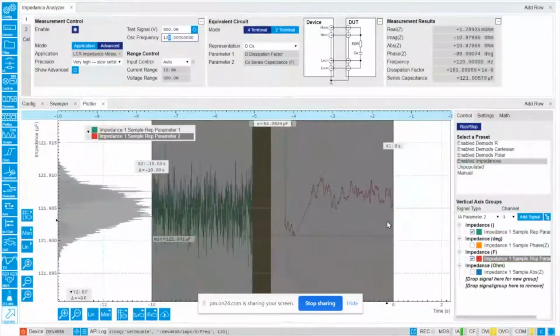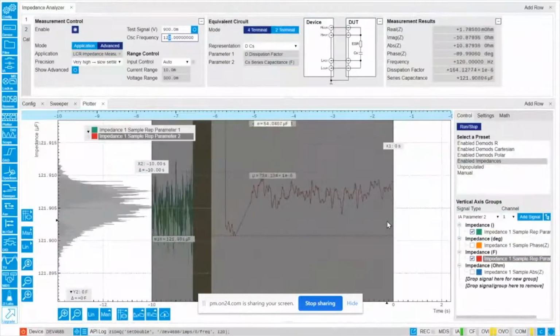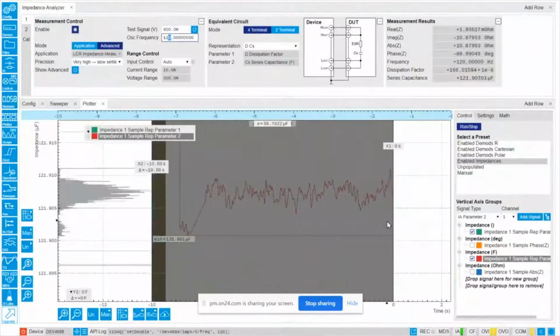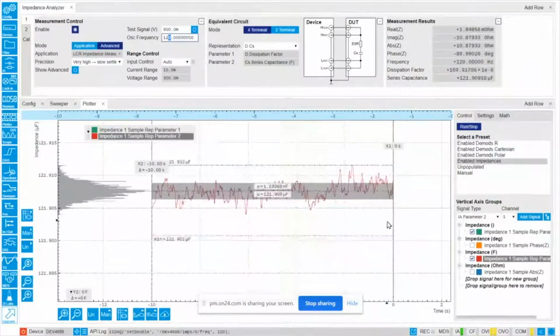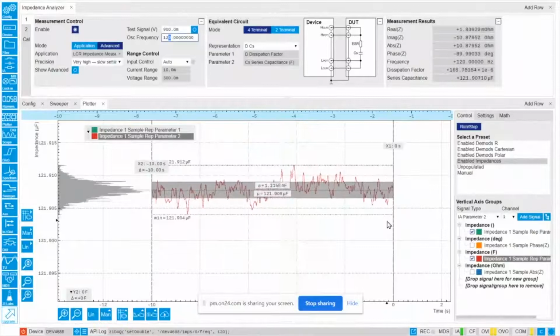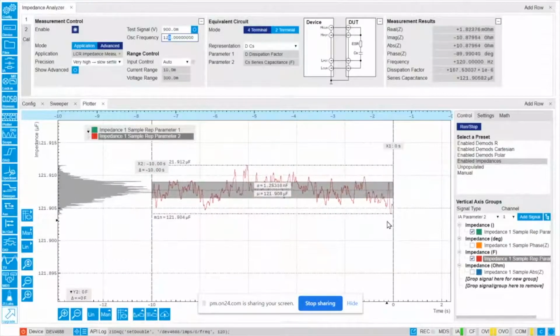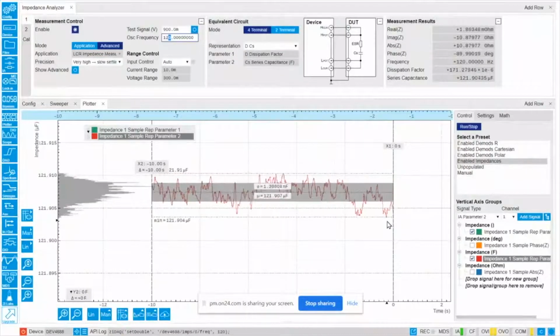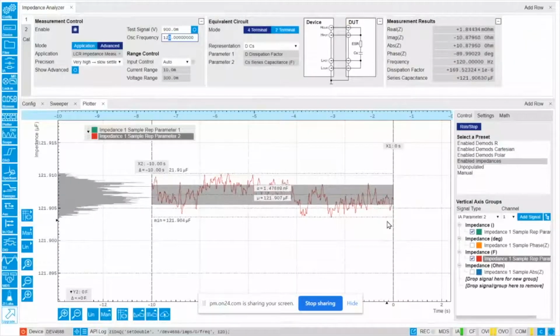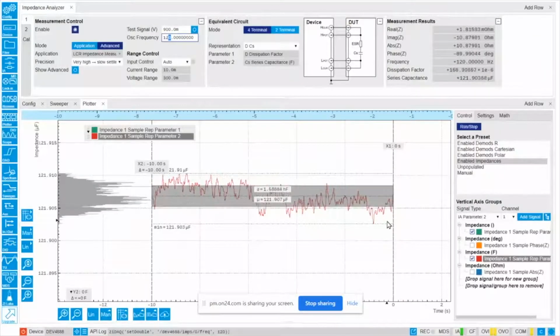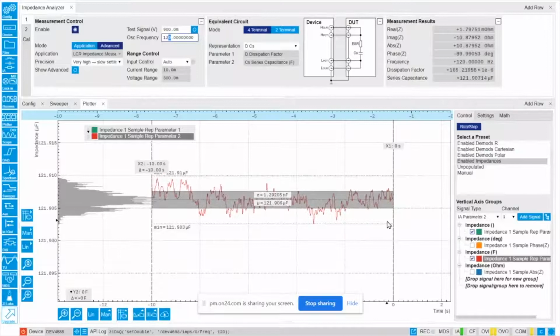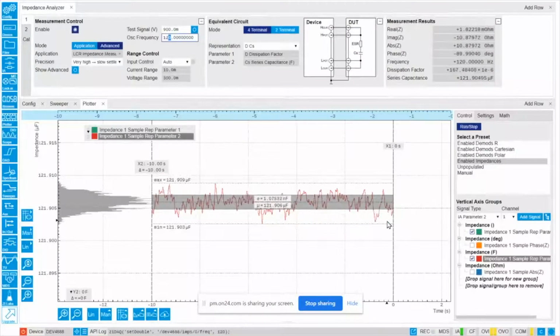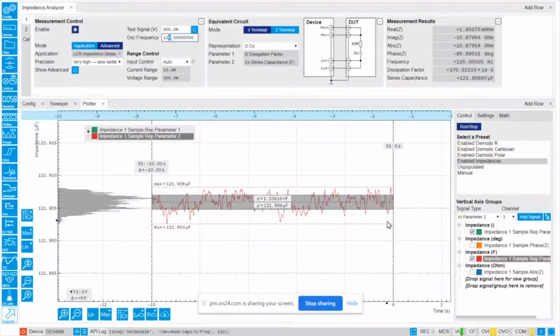Absolutely, yeah. Today, of course, we were looking at the low end of the scale. We were looking below 1 milliohm, but the MFIA can actually measure up to 1 teraohm at the low frequency end. This would be very useful for anyone looking at dielectrics or insulation. Great. Yes, you're right. We covered the low, but yeah, it's good to also mention our high value ranges.